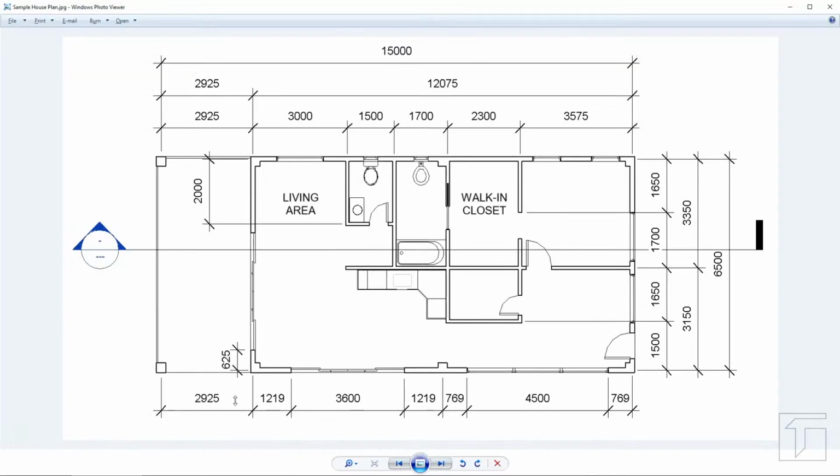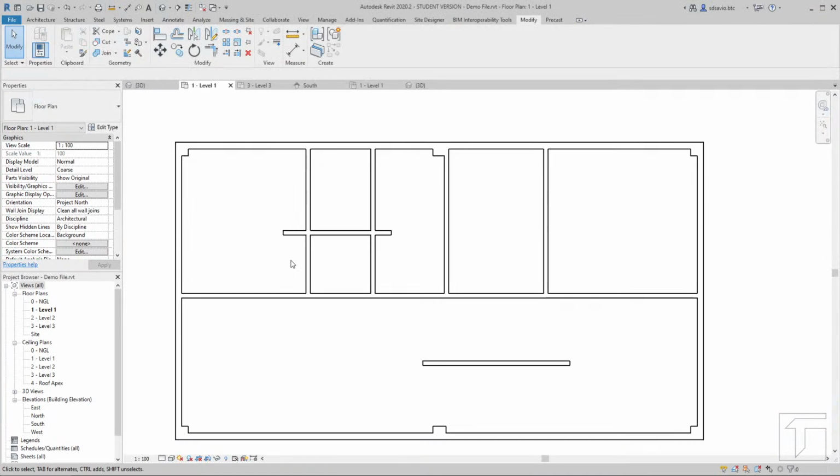So going back to our guide, for the powder room, we need this wall here. So on this corner here, okay? Now the distance also of this horizontal wall of the powder room is 2000 millimeters with respect to this upper wall here. So going back to Revit, first we need to clean this out here.